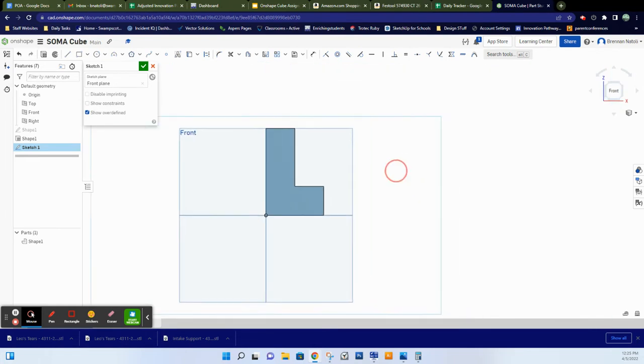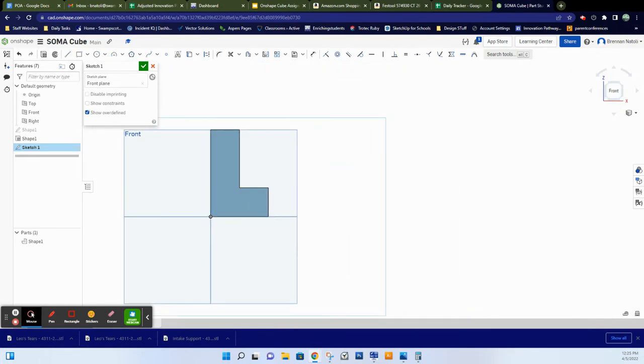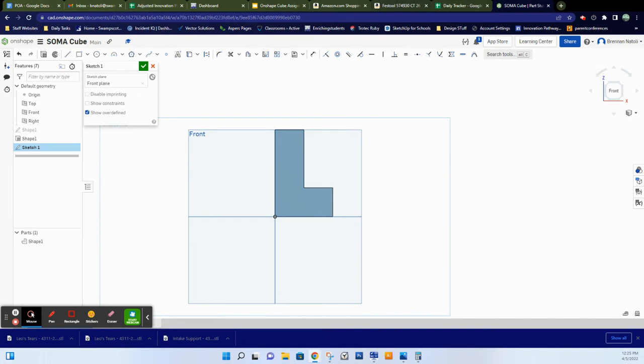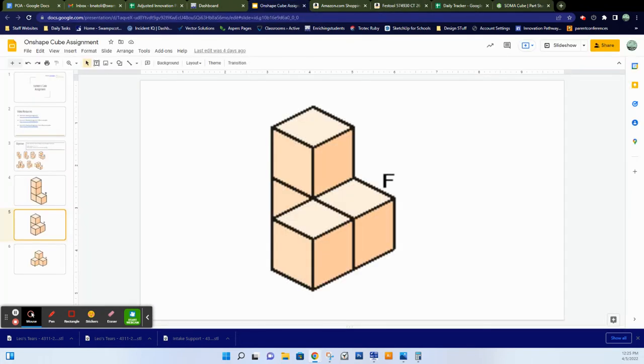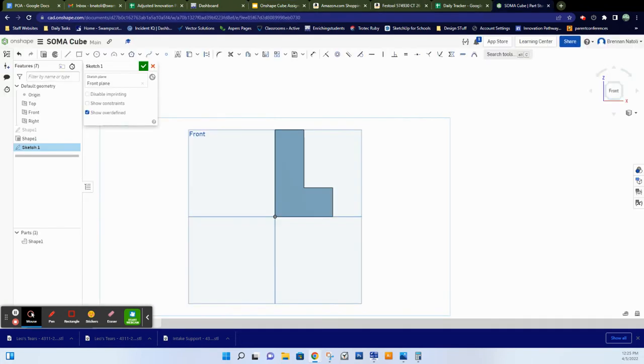Now, I don't want it on top of it, I mean, next to it, not on top of it. But I'm going to draw this shape. So we're going to draw this shape here. So let's start with the front profile. So I hit Sketch. We're on the plane. I'm going to take my line tool, and I want to draw it in reference to this origin. So I just highlight over the origin point and move over. Now, the shape we're trying to create looks something like this.